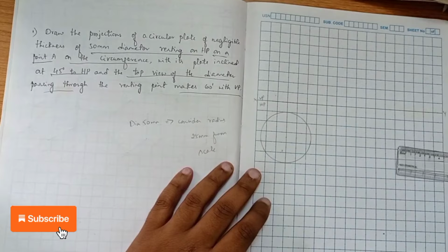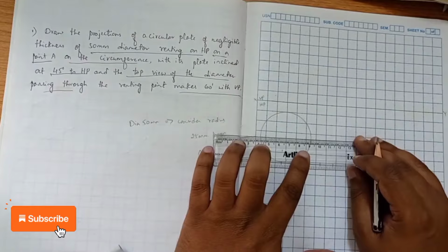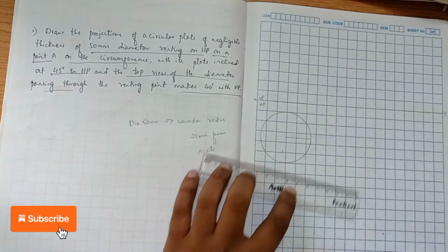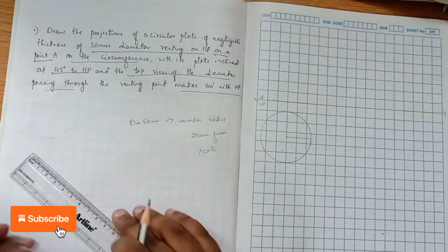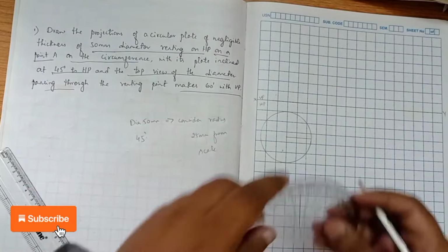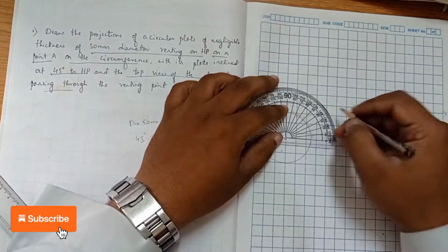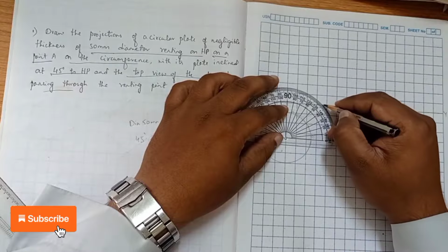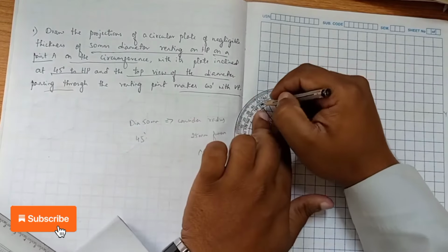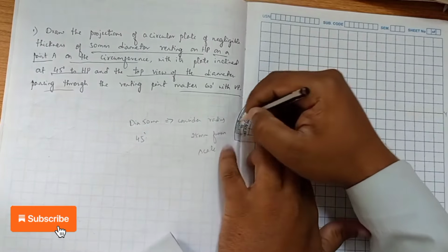Now we have to divide this circle into 8 equal parts. Okay, so for that initially I will be drawing a straight line here. Then we know the concept. So in order to divide the circle into 8 equal parts, we will be considering the 45 degree, right? So as we have found out in the external angle, so taking this point as a reference, I'll be marking at 45, 90, okay, then 135, and then 180.